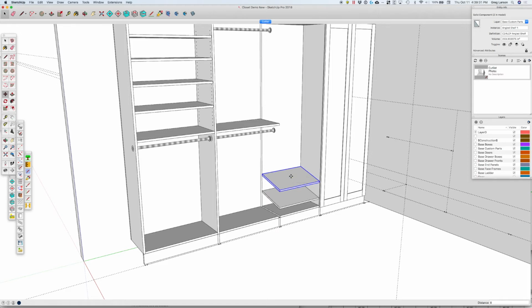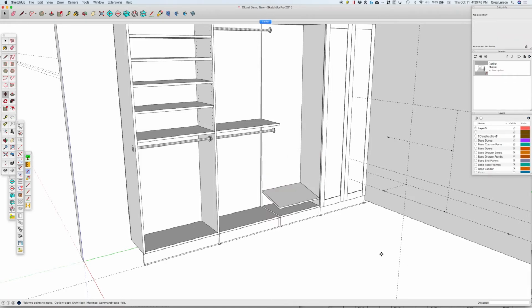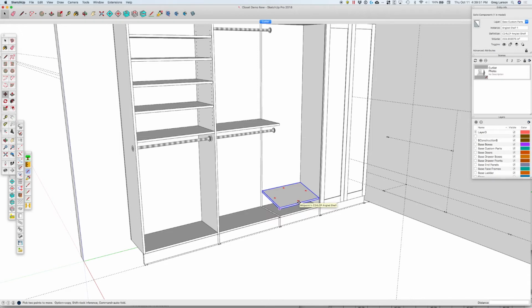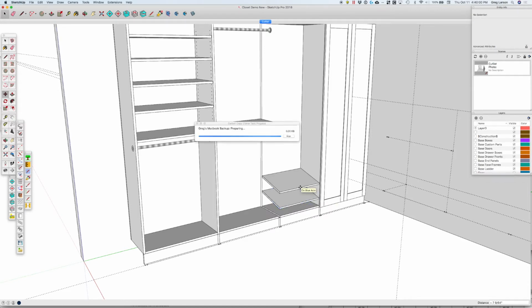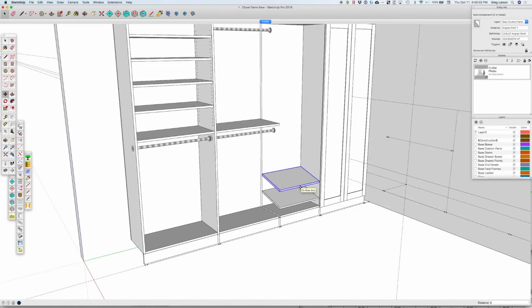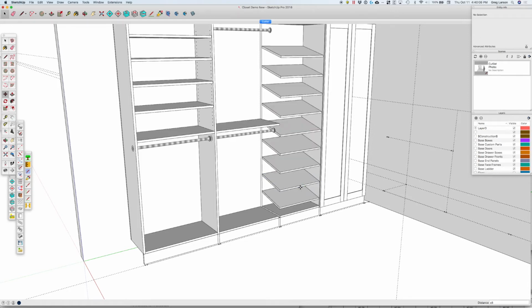Before I do anything else, I'm going to say X 8. See that down in the lower right hand corner here? Remember, don't do anything else after you type in that 8. And what that does, oops, let me just undo this, because I screwed it up by going off there. So hitting the Option key with the move command, going up the blue axis some distance, type 8, return, X8. And what that does is it does it 8 more times. So now I got 8 shelves there.